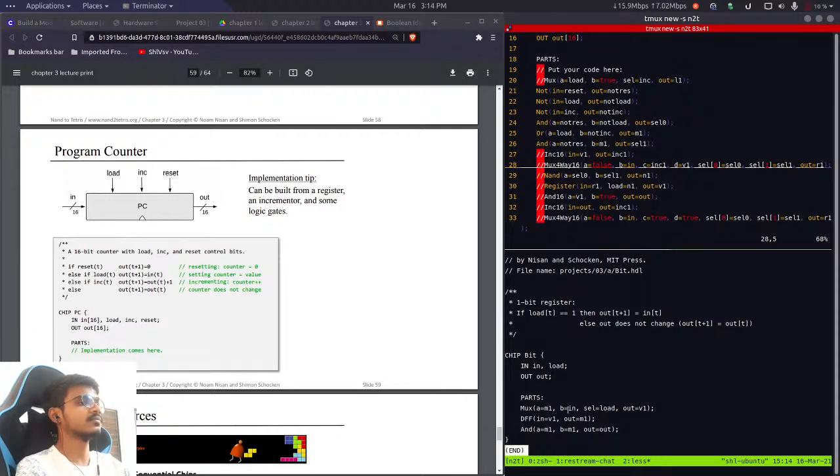So whenever the selector bit was 0, we selected whatever was inside M1. So initially there was just... because V1 was... oh wait, it is cyclical. Initially M1 and V1 both contain 0. So for the DFF the output will be 0 for M1 as well. If the load bit is 0, this will be selected, it will go over to V1. Now if the load bit is 1, we pass the input to V1 and V1 goes here and goes to the DFF. Finally we also do an AND operation to get the output.